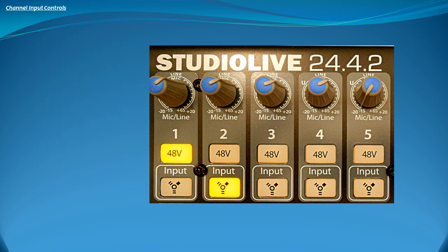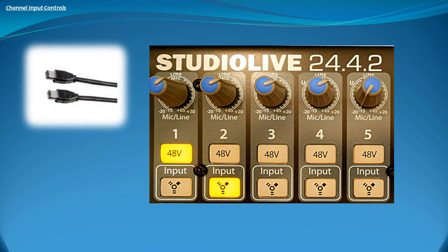The SL24.4.2 mixer uses a FireWire or 1394 connection to not only stream audio to the audio workstation computer, but also to return DAW processed audio back into the source channels. When a channel FireWire button is enabled, DAW processed audio for that channel will be inserted back into that channel and will replace the original channel signal at the channel output. What will then be heard for that channel over the loudspeakers will be the DAW processed sound.